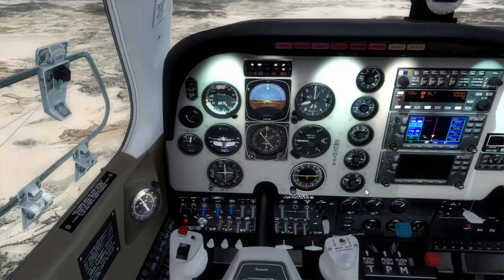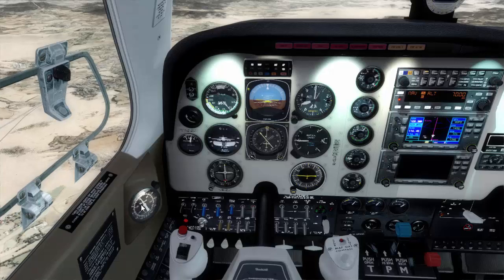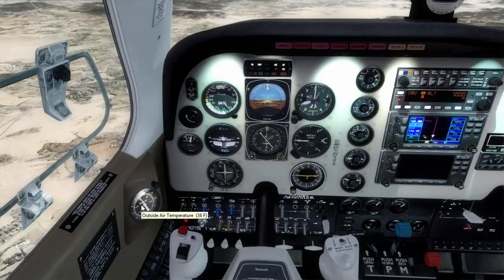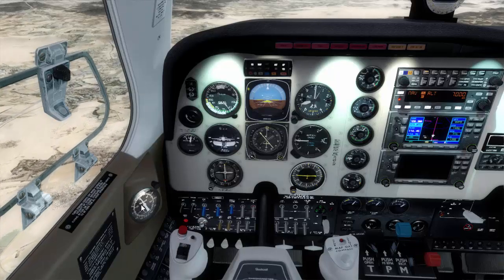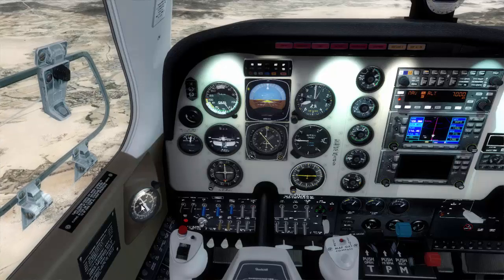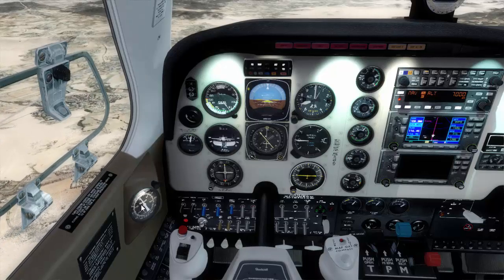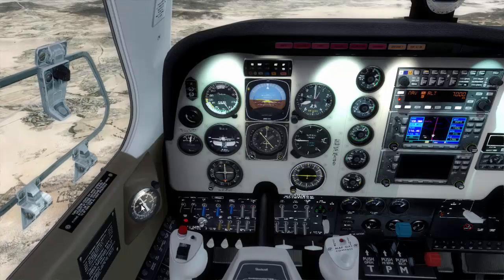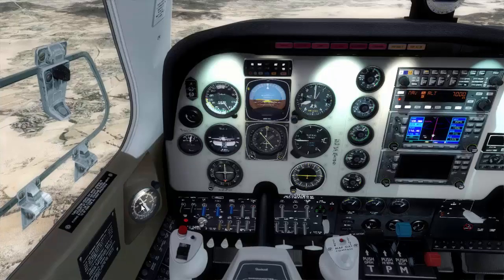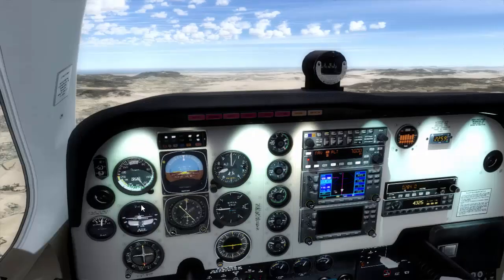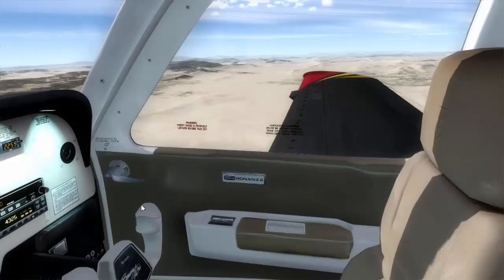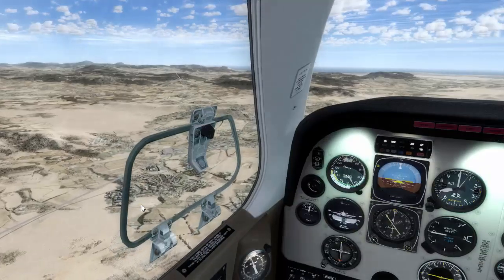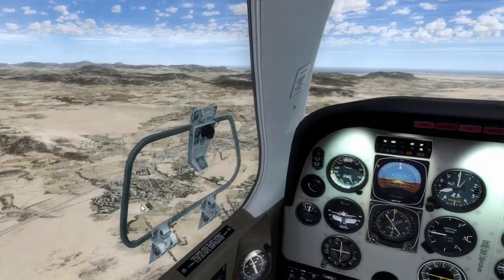So right now we have a value there because we are applying power to the engine, and it gives the inches of mercury of the fuel mixture inside our engine. And right now we have a different temperature, of course. We have 36 Fahrenheit degrees there. So we are flying at a lower altitude, and remember that when we are descending, we need to enrich the mixture. But don't worry about enriching the mixture right now. At different points, that means at different altitudes, we will be calculating the EGT peak as a reference point, as I said before, to decide if we fly rich or lean.